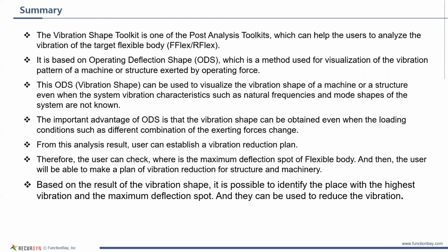So in summary, as we've seen, this toolkit is part of the post-analysis toolkits, and it's really for analyzing and understanding vibrations. And it's using this operating deflection shape, which includes all the conditions occurring during the duty cycle, in the time domain. And so we can visualize vibrational shapes, and we don't need to separately calculate natural frequencies and mode shapes.